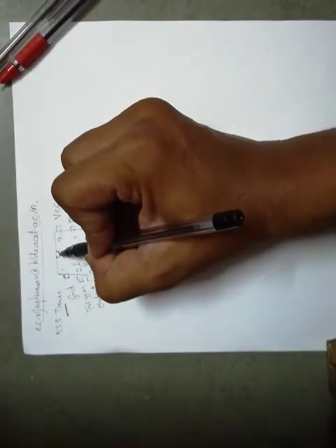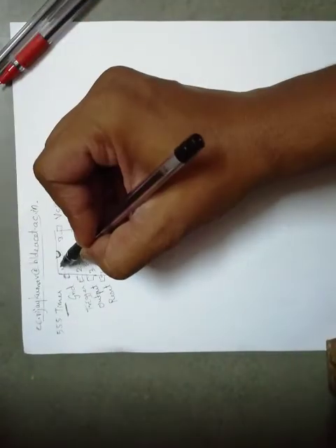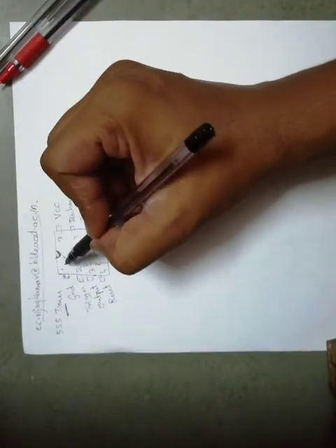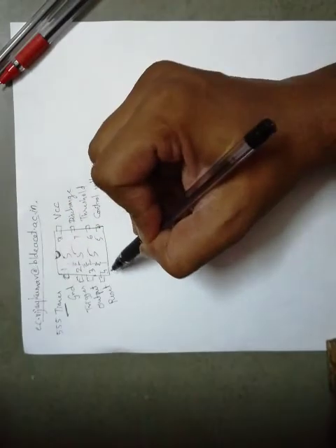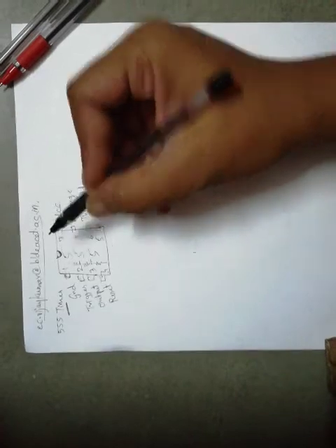There is a notch. Every IC, integrated circuit, has a notch. It is used for identifying which is the upper part, which is the lower part, and how the pins are counted. Pins are counted starting from left 1 2 3 4, then bottom up 5 6 7 8. So we have 8 pins for the 555 timer.